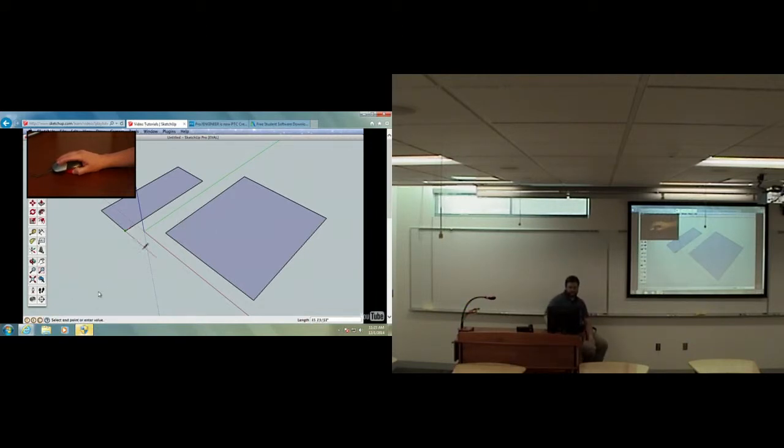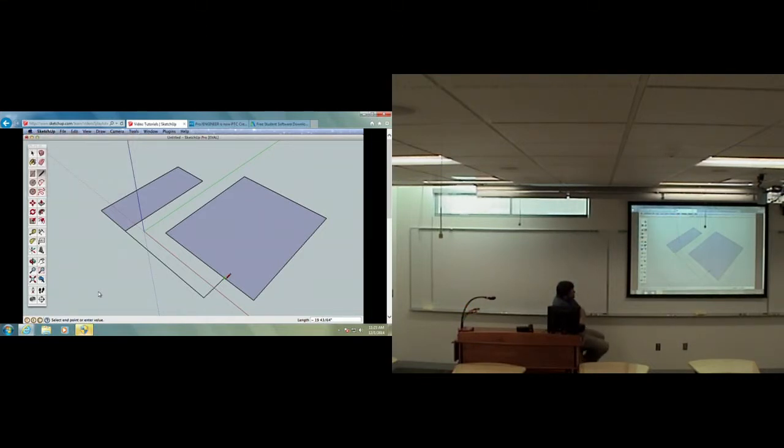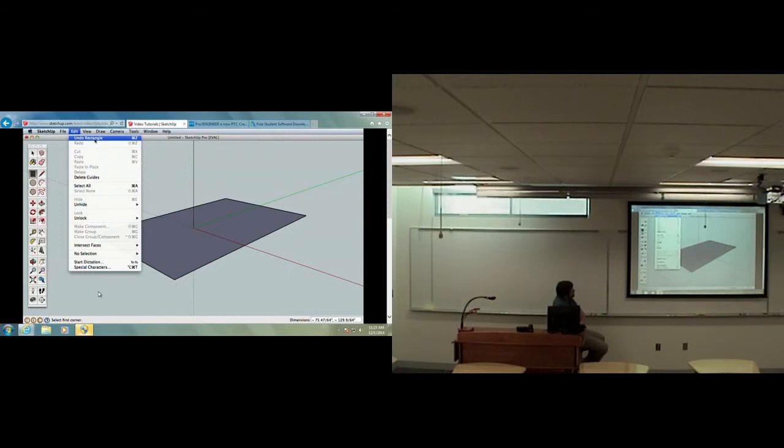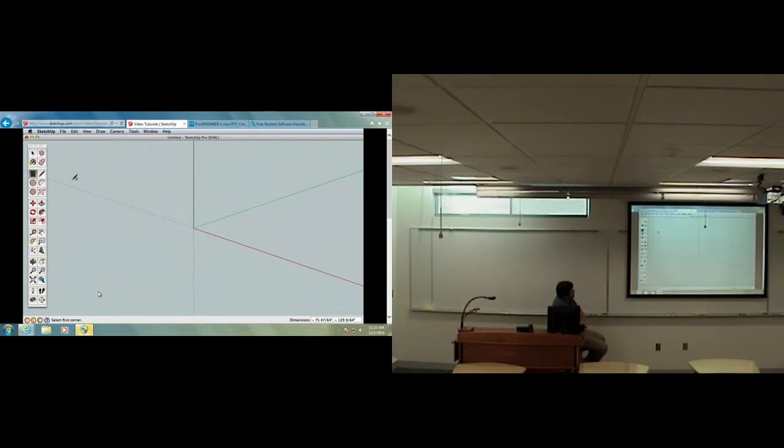Unless we specifically ask you to click and drag your mouse button, always click and release to start and finish each tool in action. Now, undo any rectangles by going to the Edit menu and choosing Undo. Draw another rectangle, but this time keep an eye on the lower right corner as you do. Click once to start the rectangle, pull away, and watch how the dimensions change as you adjust the rectangle size. Click again to finish the rectangle. You can be as precise with SketchUp as you'd like. Although it may not seem you are being accurate, everything you draw in SketchUp has a real-world scale. We'll learn more about this later.